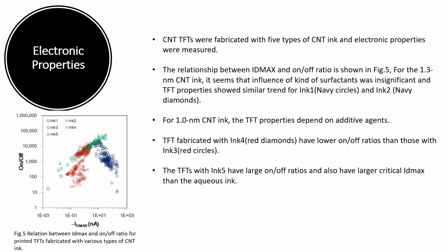For 1 nanometer CNT ink, the TFT properties depend on the additive agents. The TFTs fabricated with ink 4 have lower on-off ratios than those with ink 3. The TFTs with ink 5 have larger on-off ratios, and they have larger critical ID max than the aqueous ink.